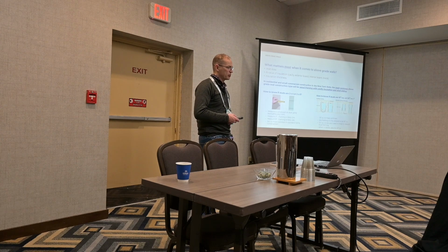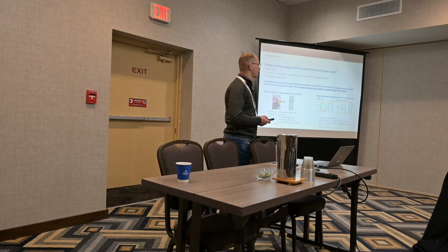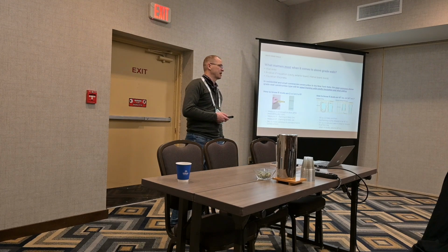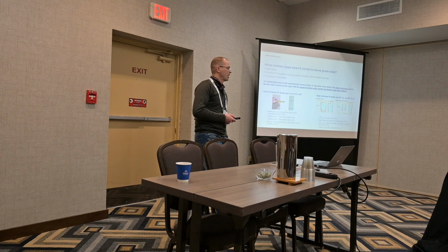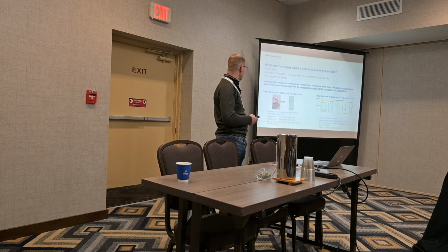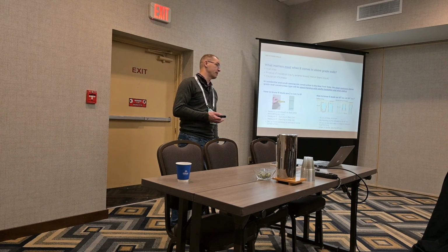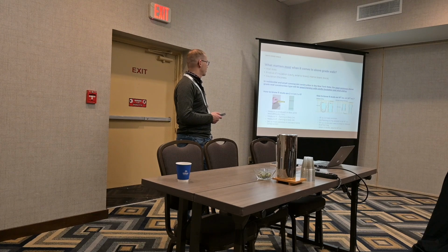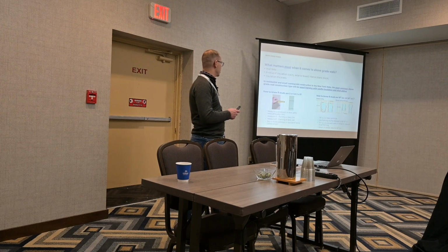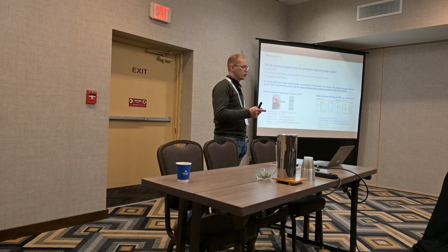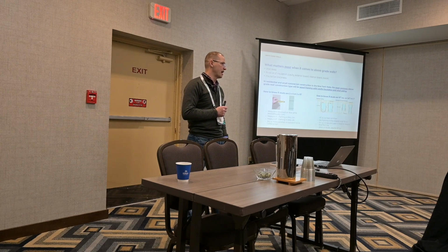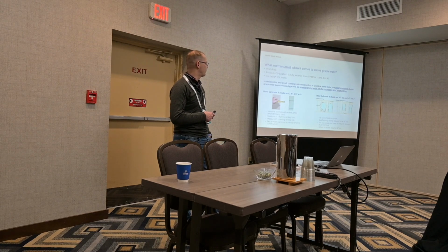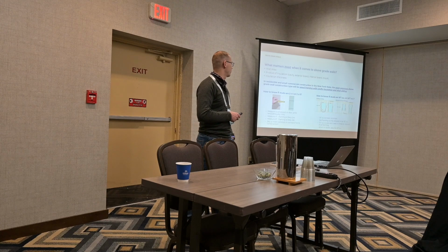In residential and small commercial construction in New York, the more common above grade wall construction type is wood framing cavity, typically 2x4, with vinyl siding on the outside. To get a good measurement, you can measure across a door jamb. That will give you a pretty close estimate of the thickness of the wall, or across the window. When you do it, do not include the trim area. The trim area will stick out a little bit and add to that measurement, but typically around 4 to 4.5 inches is your wall thickness on a 2x4 if you're measuring across the door jamb.